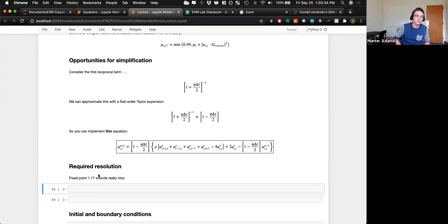So you need to be very careful about initial conditions for your drum so that you're not giving it so much energy that, when it drops from your initial conditions to the other side and back and rings, you're exceeding ±1 and causing an overflow.